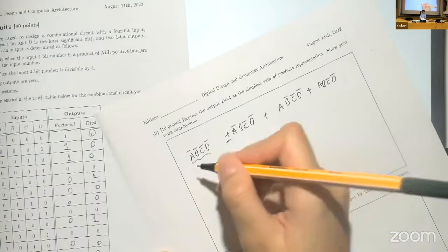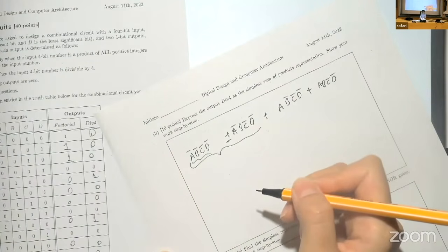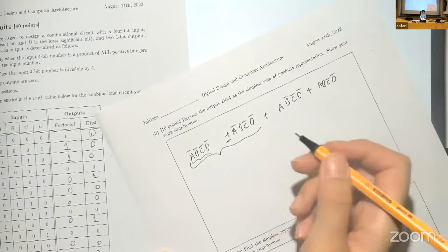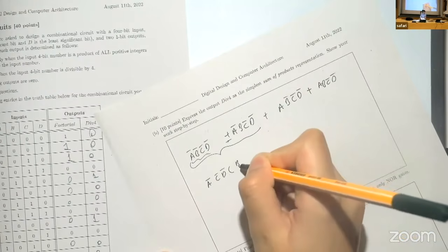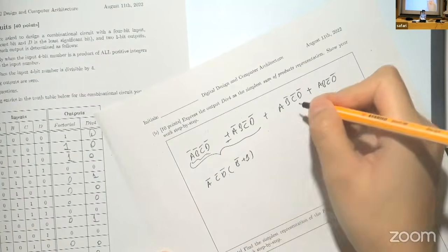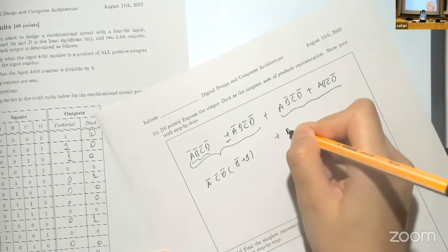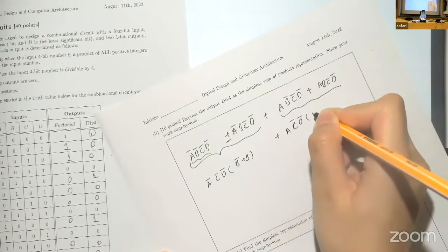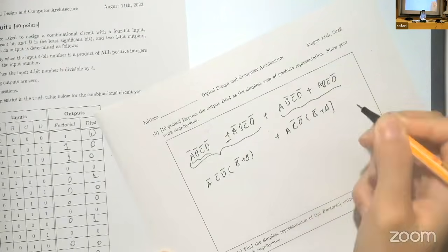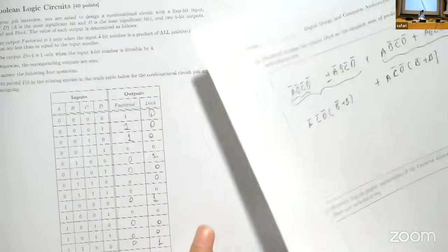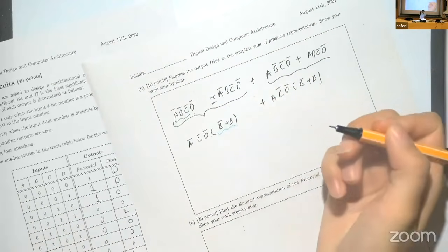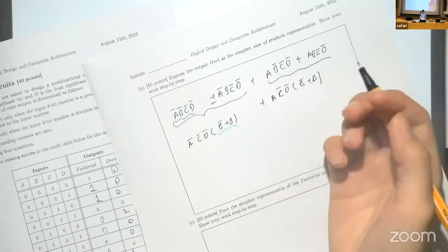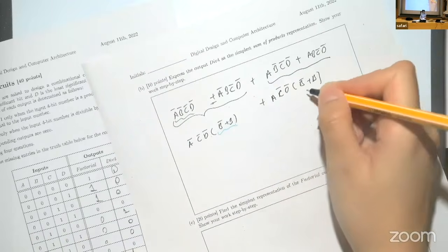The way we simplify is we merge the terms that have most entries common but differ by 1. In this one, if we take out the parentheses of A naught, C naught, and D naught, we will see that this is equal to B naught or B. And then the other one is if we take the parentheses of A, C naught, and D naught, this is also B naught or B. We need to do the simplification in this way first. So we need to first realize that B or B naught is 1 because either one of them has to be 1, and if you have at least one 1, the resulting solution is going to be 1.